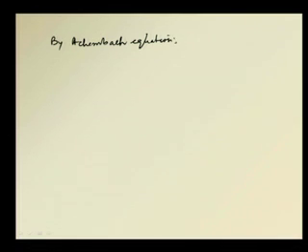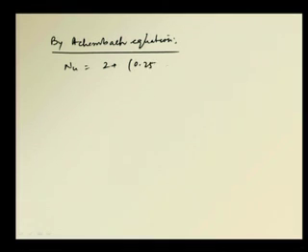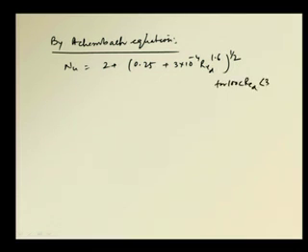If we try to find out, then according to this, Nusselt equals 2 plus (0.25 plus 3 into 10 to the power minus 4 Reynolds to the power 1.6) whole to the power half. We have just discussed this equation. This is for 100 less than Re_D less than 3 into 10 to the power 5, and Prandtl is equal to 0.71. Our Prandtl number is very close to this, and Reynolds number is also very close to 100.